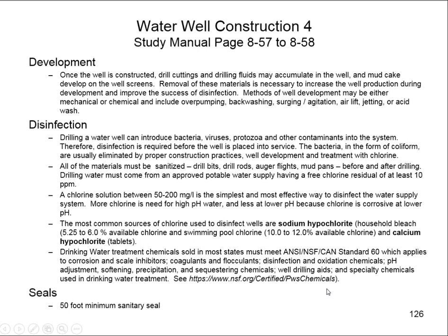Then we need to develop the well, because we could have drill cuttings or mud cake that's accumulated, and we want to increase our well production and make sure that we disinfect the well. So the kinds of well development techniques are mechanical, by over pumping or backwashing or surging, or chemical, using an acid wash.